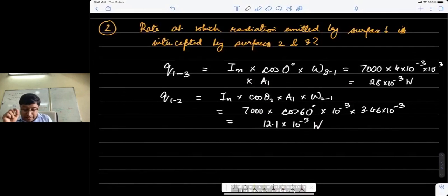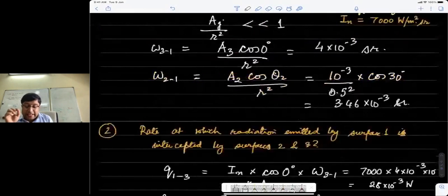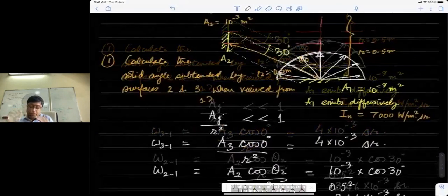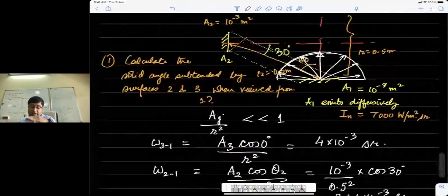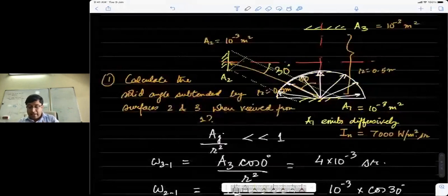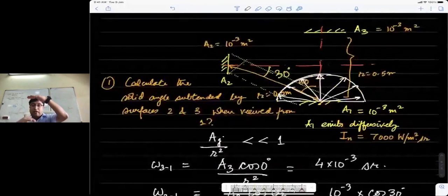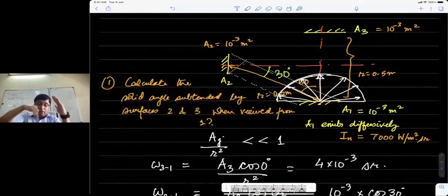Now, I can slightly change the problem and ask, what if A1 was not flat in this way? Maybe it was inclined, looking at A2, and A2 was also inclined but looking at A1. So A1 and A3 are like this, but I turn them around so they still see each other. The angle would still be 0 degrees, because the normals see each other completely.